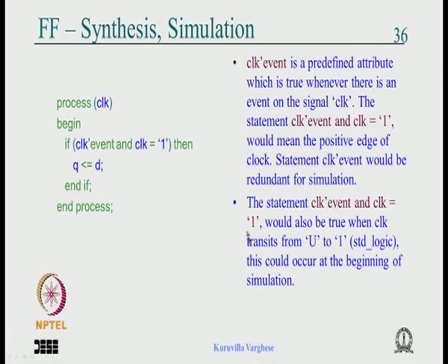So there could be some false trigger when you simulate it, which is not a very good idea, because then the simulator behavior and the synthesis behavior will be different. So at the beginning, whatever hardware you really synthesize will work differently from what you have simulated. Either you should know this fact and take care in the simulation, or you should somehow make the simulation and synthesis behavior the same. Maybe we will discuss this at the appropriate time.